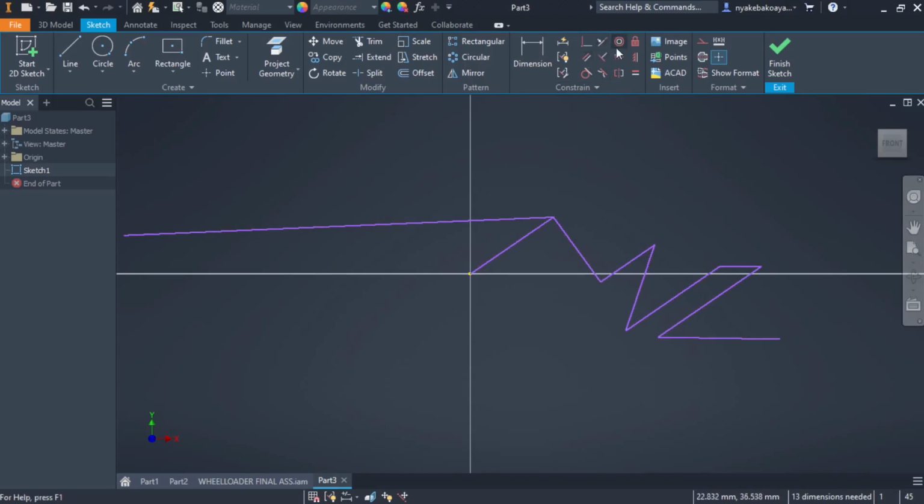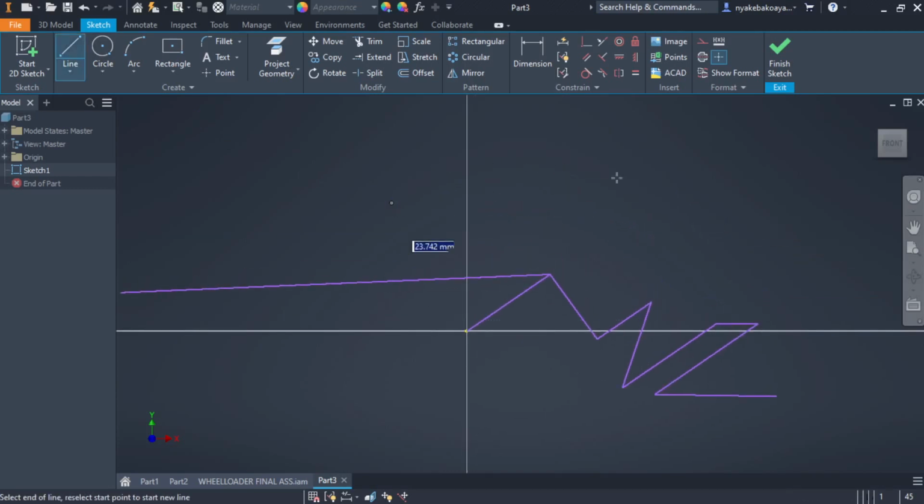All right, let's look at the other thing. We have the collinear command. From mathematics, what it does is make a line parallel as well as in line with a particular line. This is what it means. Let's say we have an arbitrary line here. Click OK. We have that line. We want this line to be collinear with this.